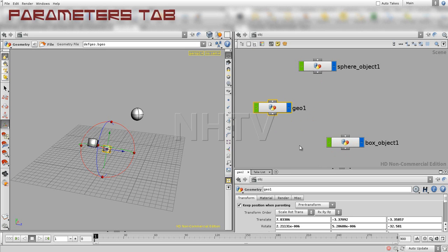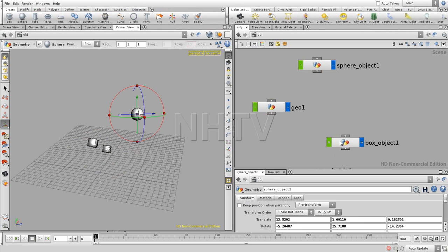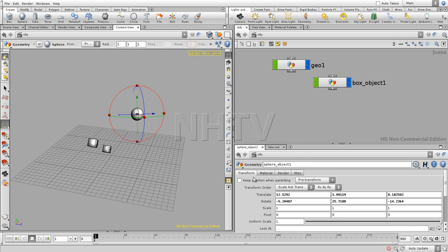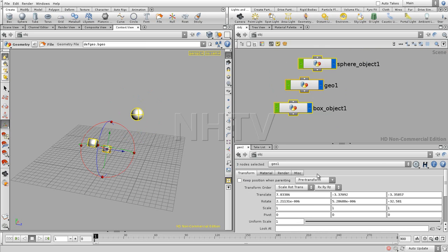Now the thing that you saw me doing was that I selected each one of those nodes to switch something on or off. Now in Maya you might be used to doing that, like in the attribute editor, you have to really click for each object a certain parameter. Now Houdini does this in a smarter way. If you select all of the objects, it's going to check right over here in the parameters which of the elements are in common.